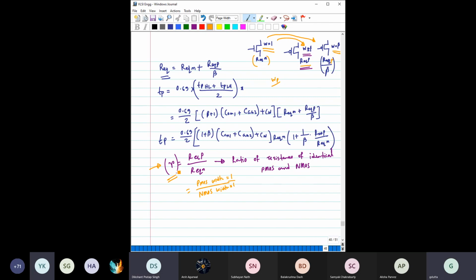You have understood, right? Okay, so if I make the PMOS R times that of the NMOS, can you comment what would be the relation between charging time and discharging time, or TPHL and TPLH?